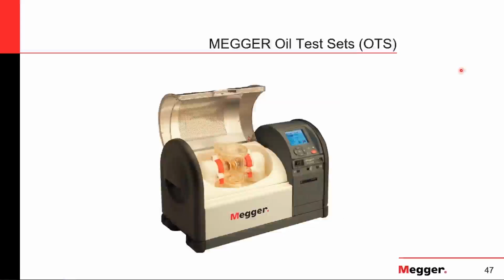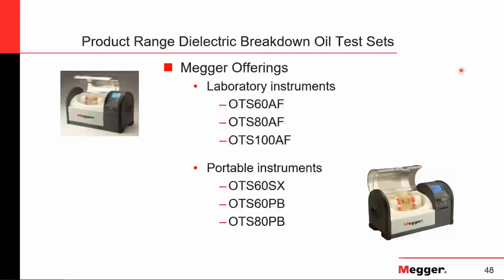On the vessel part, clear material as we discussed, easy way to change or interchange the electrodes depending on the type of test we are performing, accurate and smooth gap gauges. These are made out of anodized aluminum, and an easy mechanism to adjust the gap, and really important, lock it in place when we finalize adjusting that distance between the electrodes.